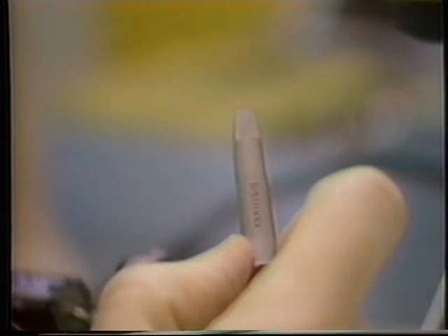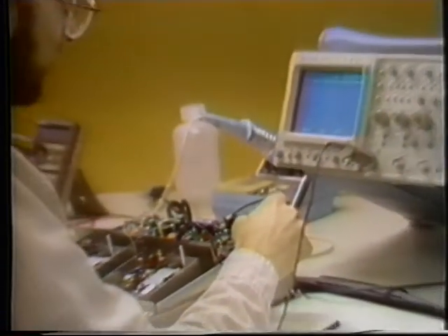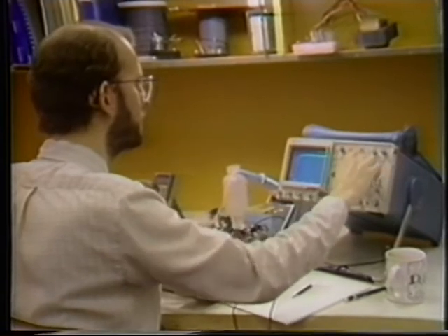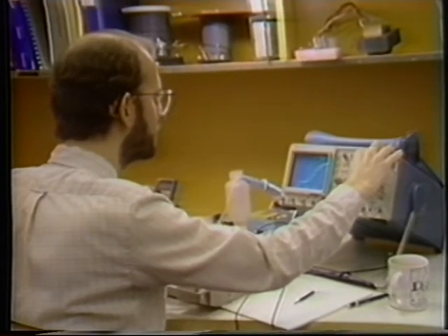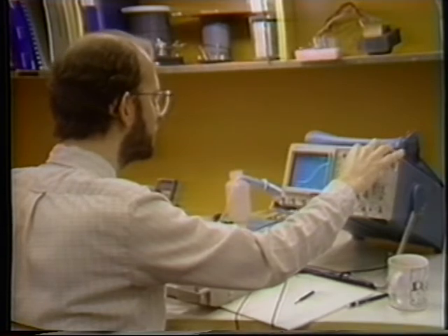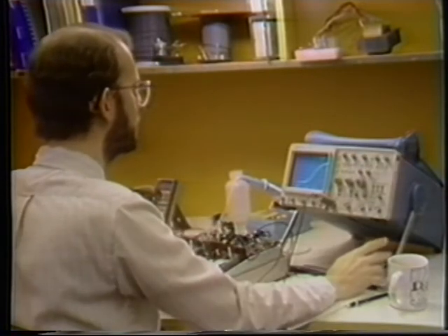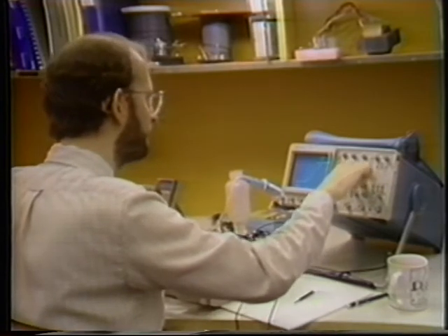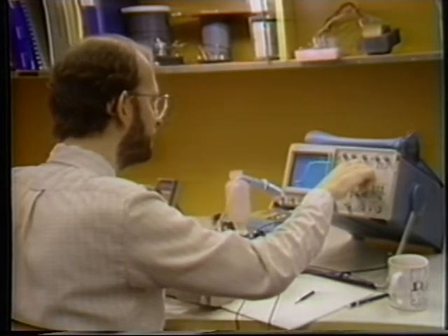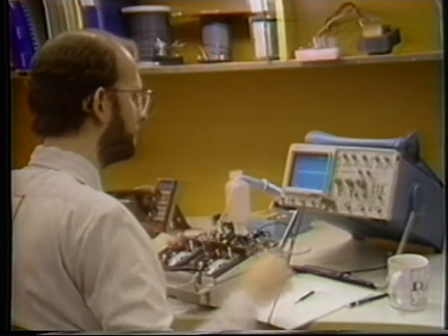Now, this circuit is typical of a simple 100 megahertz high Z passive probe. Higher bandwidth probes use more complicated termination schemes and more adjustable components to adequately control transient response, but the guiding principles are the same. So with your trusty high Z probe, you're ready for anything, right? Well, not exactly. Impressive as high Z passive probes are, they do have limitations. If you need to measure the rise time of an ECL gate and apply the same high Z probe, you may find a much slower rise time than you expected. As we'll see, high Z probes are not the best choice for fast rise time measurements.